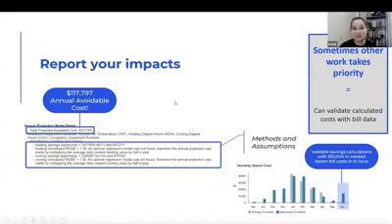So this annual avoidable cost is a really big number. It's $118,000. If I was an energy manager, I would look at that and I'd be like, ooh, that doesn't seem right. I want to know how they got that number, so I can see the methodology that's used. I can validate it with bill data. In this particular case, I can say it only was a problem for half of the month of June. I wasted $10,000. But I would probably also know that this is a problem when I get into a different season. So maybe I'm not going to take that full $118,000, or maybe I will. You could make that sort of educated decision and validate that calculated cost.